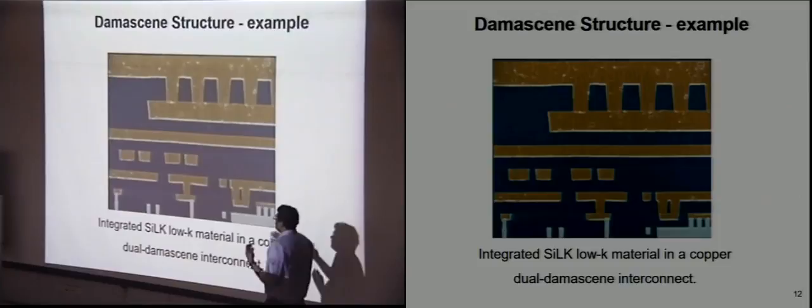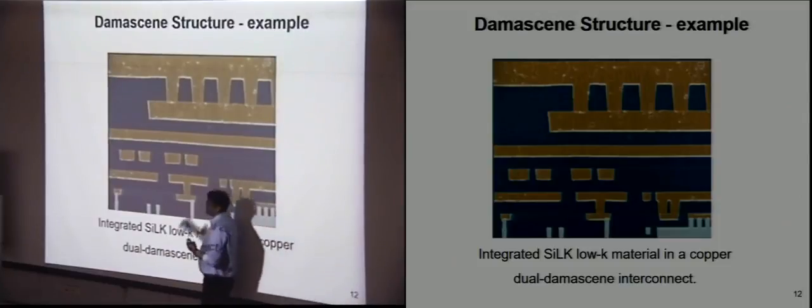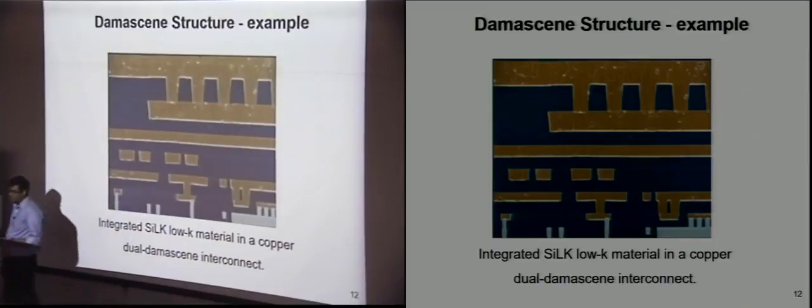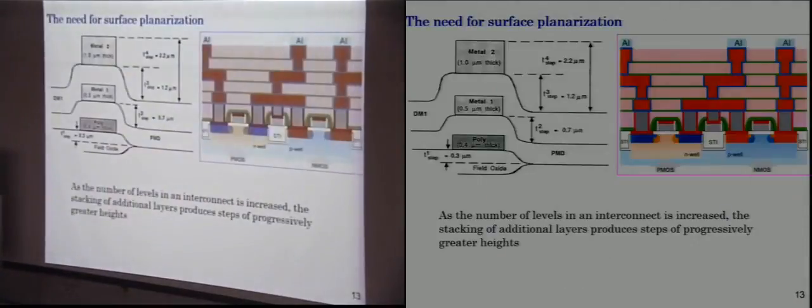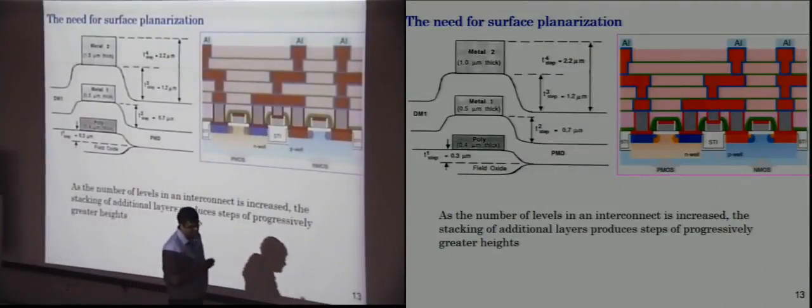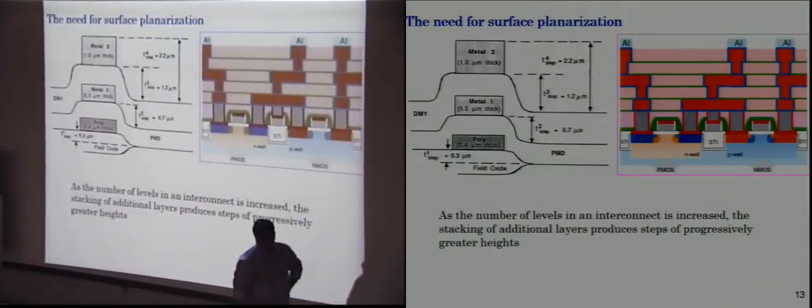You could have up to 9 or 13 metal layers being built up one by one. We will see later on a process flow on how you would build up a couple of these layers. Okay. So the copper Damascene process is very important and copper is a very heavily utilized material for metallization.